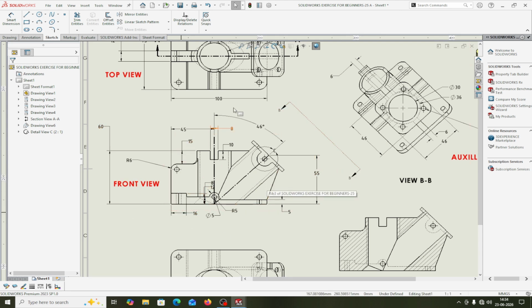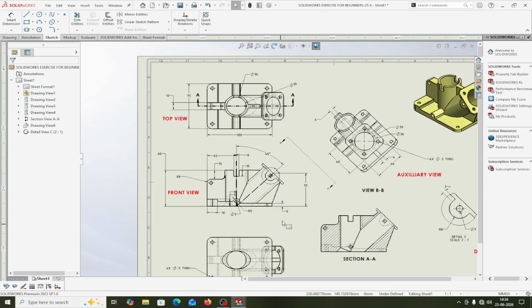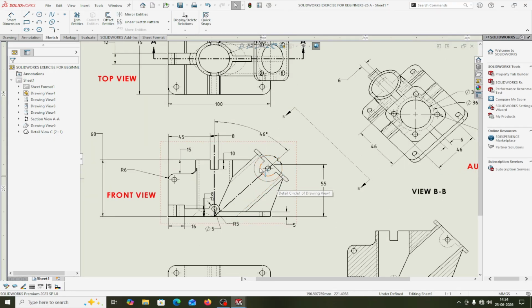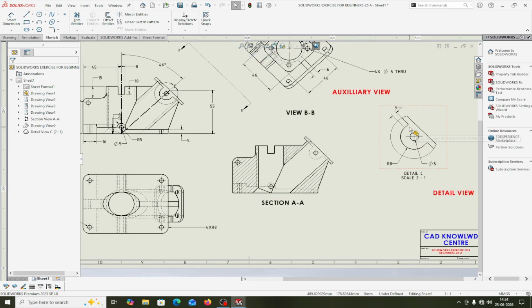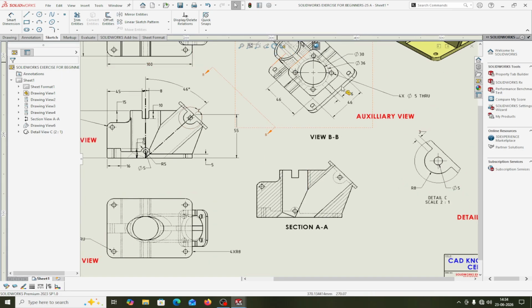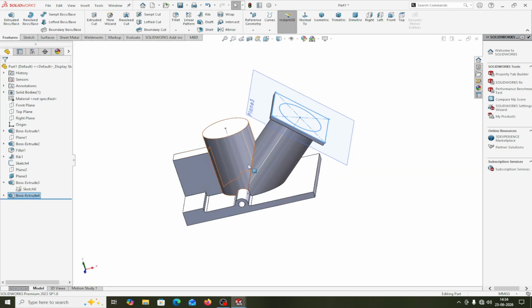Now there is an extrude cut portion, or first I provide the fillet here. First I will make this profile here. You will see the detail of this one here. This straight portion is 3 mm, this is an 8 mm radius, and a 5 mm circle. All holes are 5 mm diameter. First I will make this detailed part, the window part.